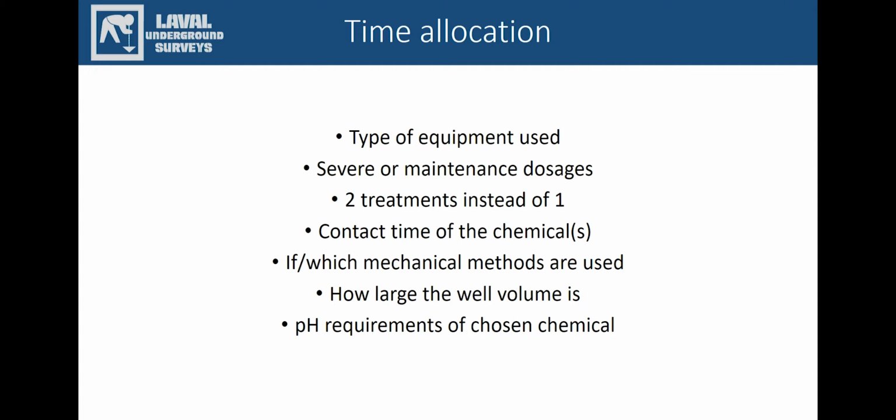The upside to doing this is that within your initial treatment, though half of the sitting time is used, you may have a clean enough well to pull off the second dosage. Using the camera or doing a post-treatment water test will always determine if this is the right option for this project. Different chemicals require different contact times. Always check with your chemical provider for more information on what's recommended.